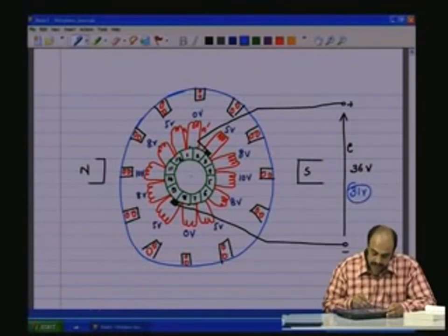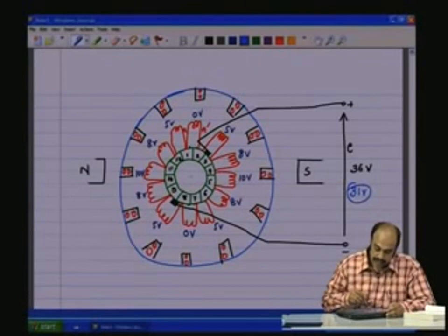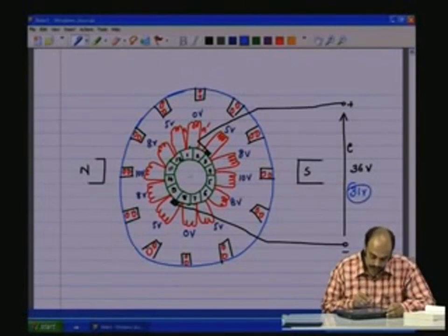In the earlier position, when it was kept at the orthogonal position in the neutral zone, any coil at that position would have 0 volts, and therefore the brush will not short the coil, and even if it shorts there is no circulating current. Here, because the brush is not in the neutral zone, at the point where the commutator segments change over, the coils are shorted.